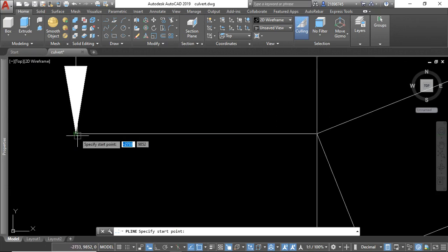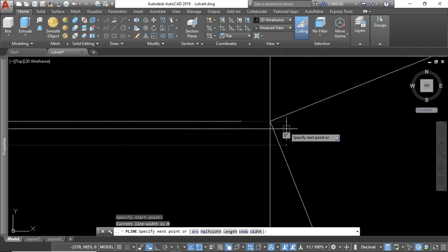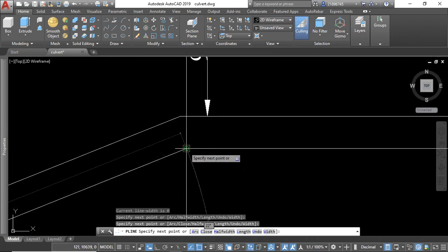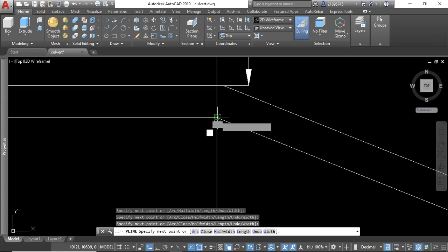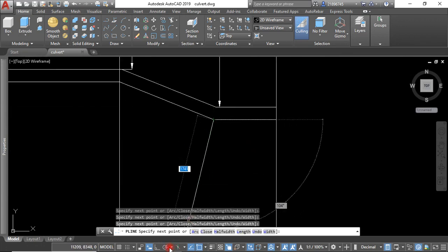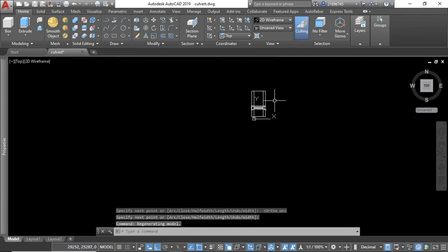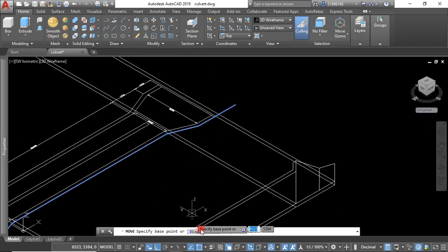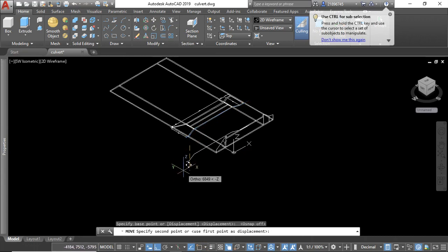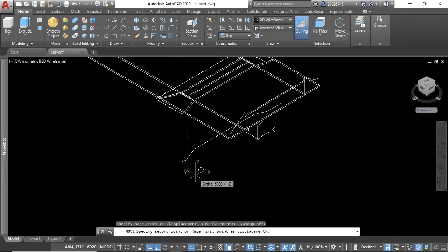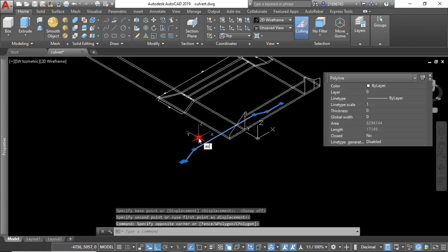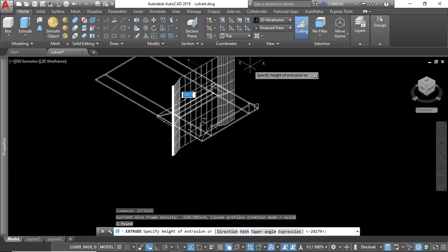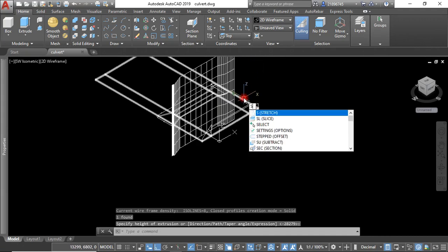So you can just come here like this, here, maybe the rest we can just pull it away. So we come back, then that is the line. So we come here and drag it, and make sure you drag it in a vertical way, and we can now extrude it again. And if we extrude, we just make sure it goes past the solid, and then we type slice.